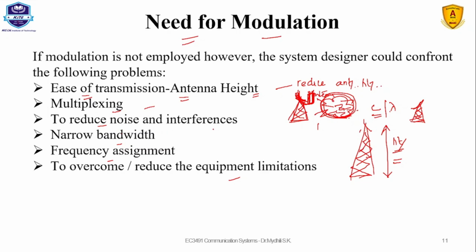When we are talking about modulation techniques, this effectively reduces noise and interference. And for narrowing the bandwidth it is also very important. Narrowing the bandwidth means that instead of allocating a signal over a wide capacity, we can allocate the same signal in a smaller bandwidth or space. That is very important, and easier when we go for modulation.